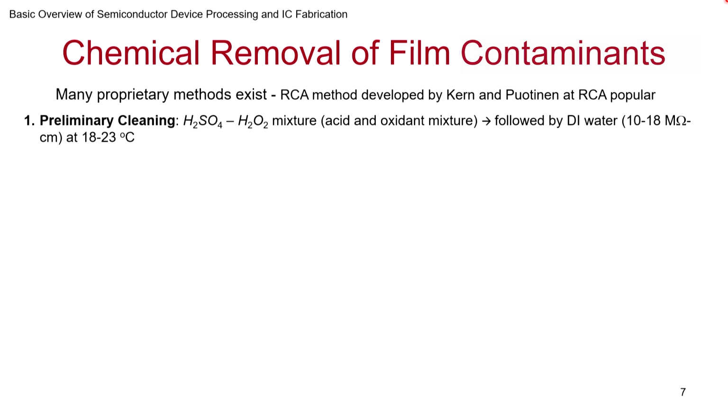That way the water will be an extremely good solvent. Anything that comes, it will dissolve very well because there are no ions present in it, and also it will not contaminate anything because there are no ions present to settle down and react with anything. Now how do you know how good the DI water is? Usually you check the resistivity of the water.